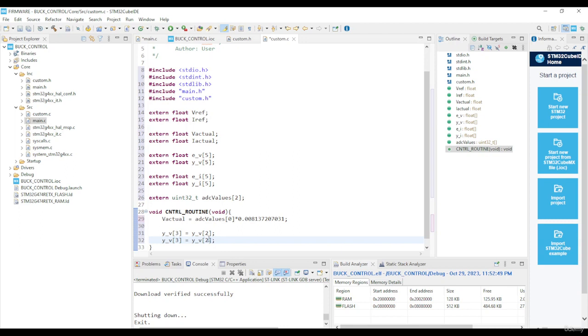So there are position forms and there are velocity forms, and what the velocity form does is it implicitly keeps track of the history. So integral windup is not so much a huge problem anymore with this type of system, because the function itself just keeps track of the history. And that's sort of why I like it a lot. So that's what that is basically.